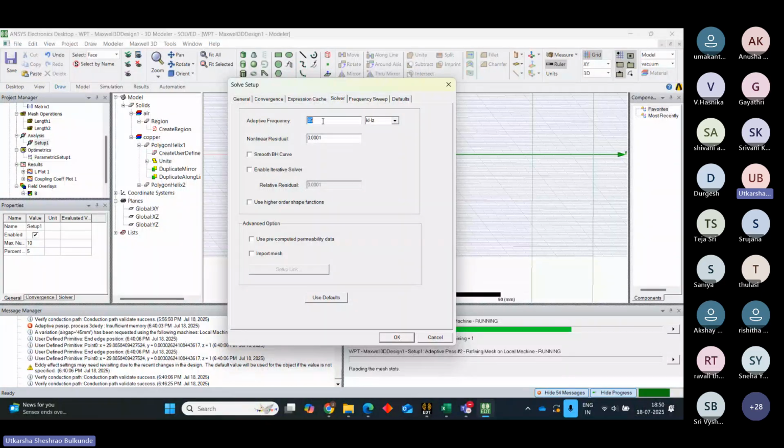For example, if my insulation limitation is 2 kilovolts, then my voltage drop should not exceed 2 kilovolts, right? For that, I should know the inductance of my coil, I times XL, right? That is also one of the reasons why I need the self inductance of my coil.